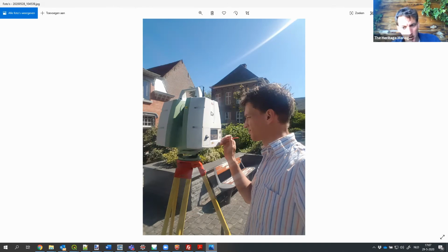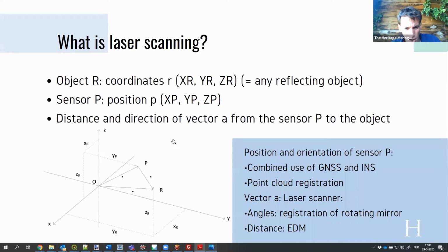From that starting position, this is the origin of your initial coordinate reference system. From that origin, you will measure a certain horizontal angular increment and a vertical angular increment. You will measure your distances, and combined with that, you will have a local coordinate system, a local point cloud, where all the points are then converted to Cartesian coordinates. And that's actually what's happening here.